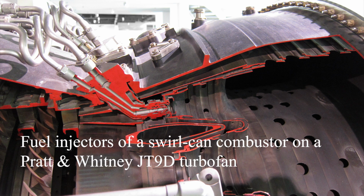This injector blasts a sheet of fuel with a stream of air, atomizing the fuel into homogeneous droplets. This type of fuel injector led to the first smokeless combustors. The air used is just some of the primary air that is diverted through the injector, rather than the swirler. This type of injector also requires lower fuel pressures than the pressure atomizing type.